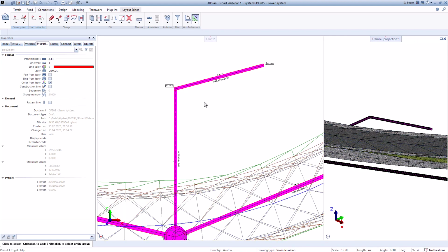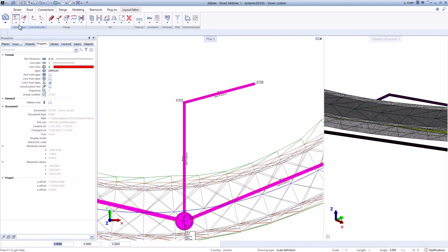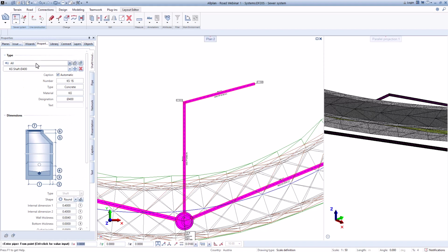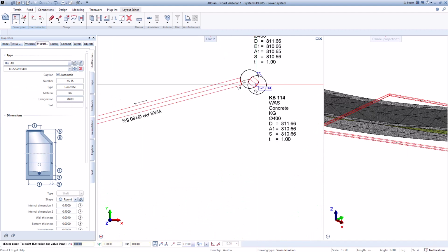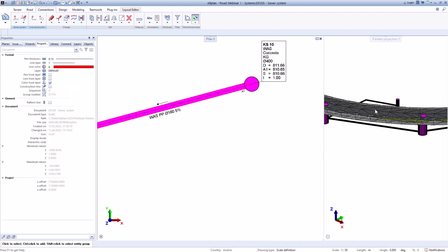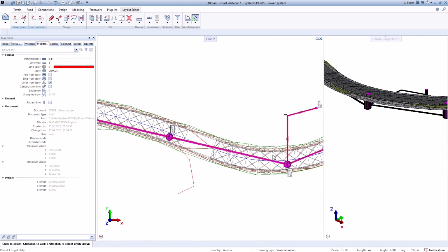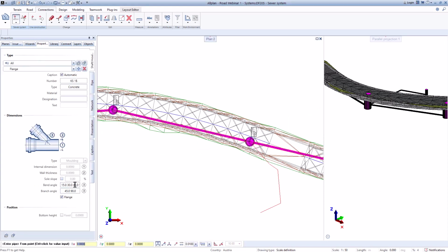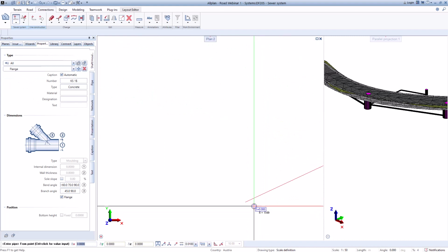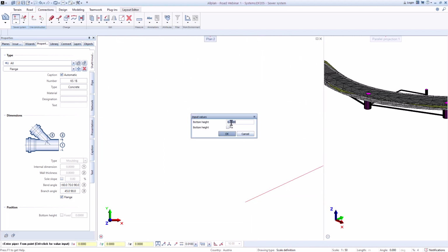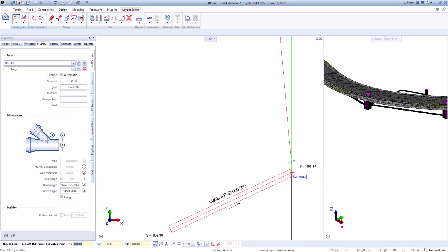Okay, and at the end we will again give a shaft. On the shaft, the house is then connected. The pipes from the house are then connected to this shaft that has a bottom and top height that you can always change by the function Modify Height. So move to another house, Control, click, elevation of the bottom, and draw the pipes.